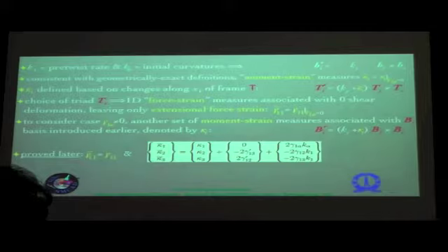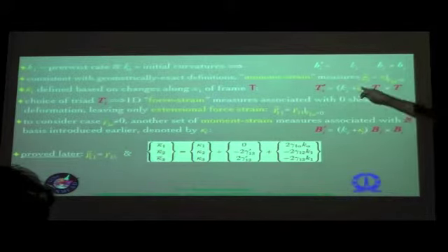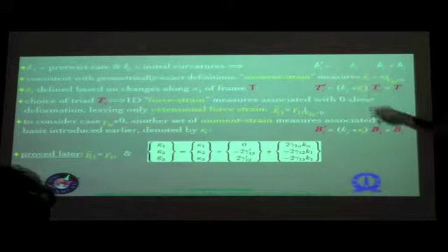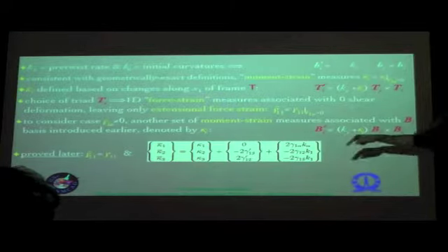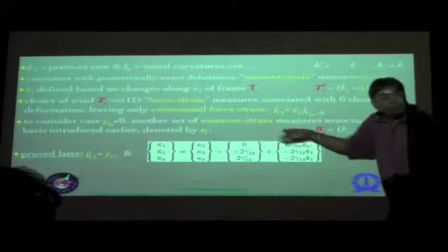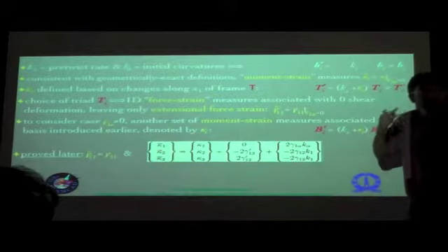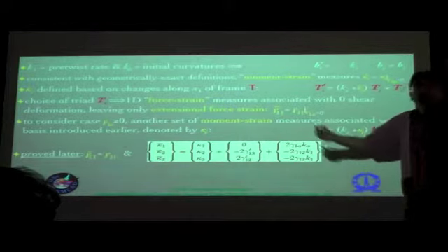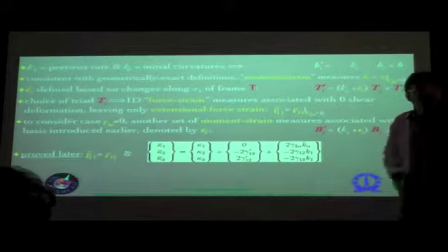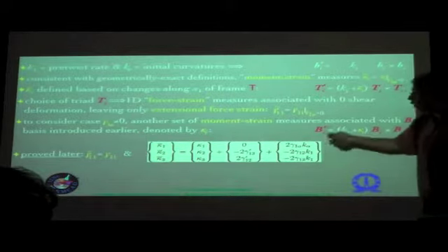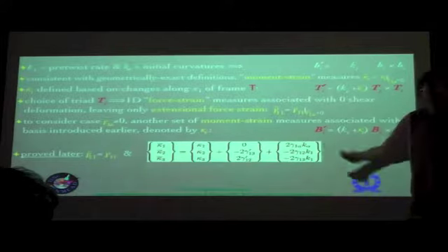So this is the relationship between the two different ways of defining these quantities, and it's quite clear that for the leading order terms this may not make much of a difference. In any case, the transverse shear strain is not something which appears in the leading or so-called zeroth order approximation. It's a higher order quantity which comes in the first order approximation.